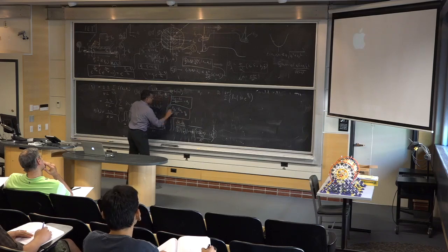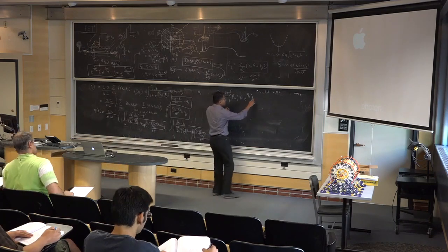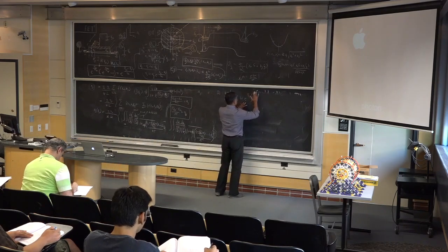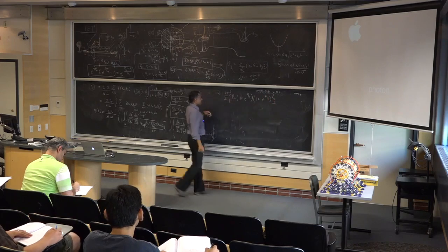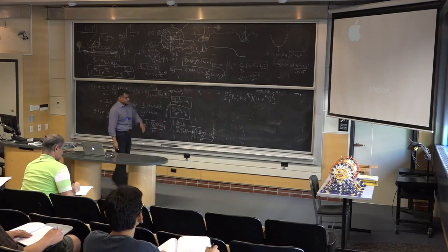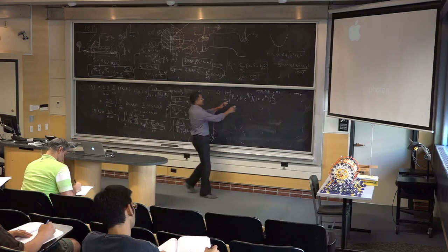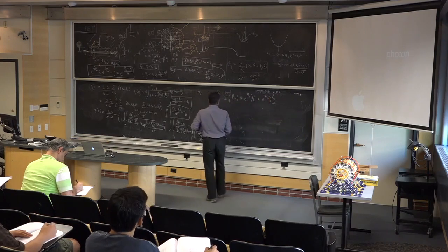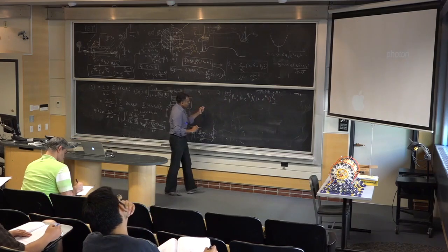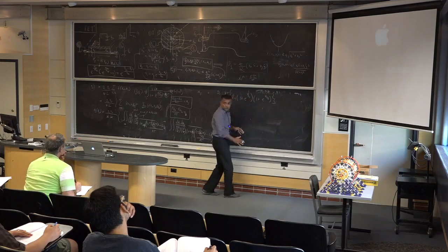Drain. Right? And what you'll get is plus natural log of e to the power that, but you can now see I just multiplied the two, right? Because if you remember, I claimed a lot of math in semiconductor physics happens in exponential space, and that's an example, right? So you get log of 1 plus something plus log of something else, you get a product, and you see very interestingly that if the source and the drain have the same Fermi level, you get log of 1 plus this whole square, right?